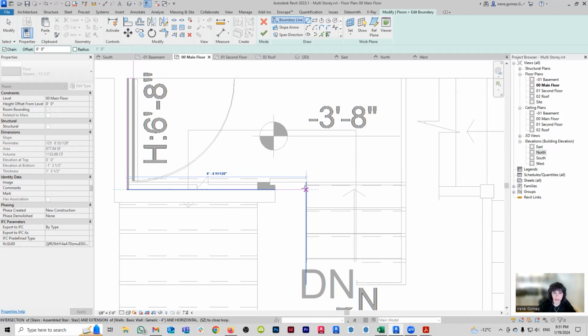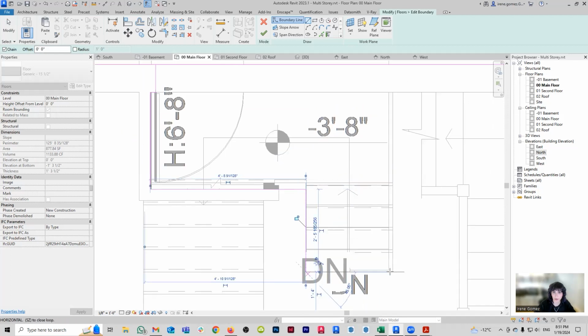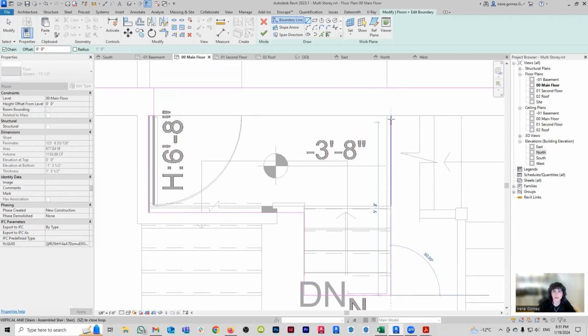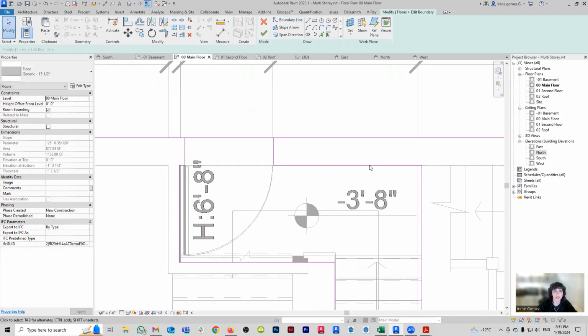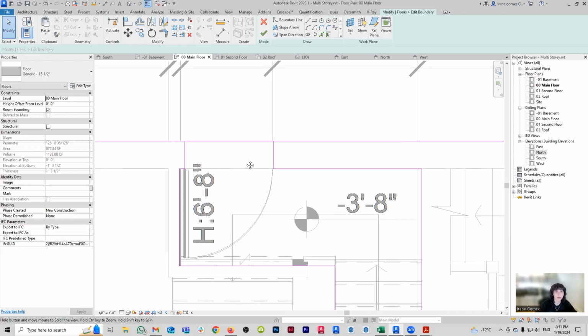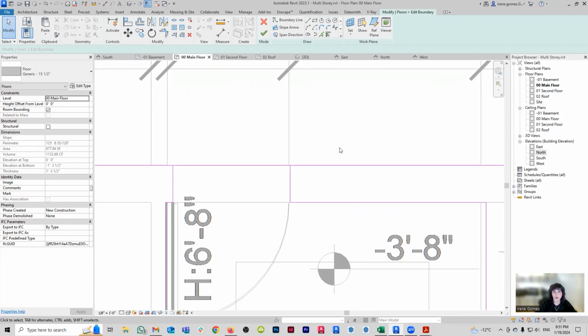I'm going to leave that opening there a little bit, and then I'm going to bring it to whatever my stairs are. Not sure if that's the real stair or the fake stair. And the thing is that, see, I'm not cutting all the way to the end of the wall here. That's because, remember, you still have that wall, slab, wall. So you do not want to leave an opening there. But here, where we have the door, we do. So we're going to use the SL split tool to cut this line into two. And then we're going to go TR for trim, trim, trim, trim, trim. And we're going to say yes.